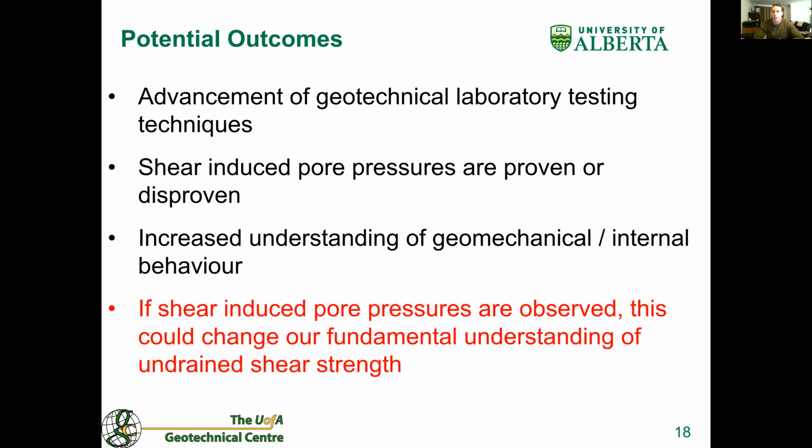This information can then be further applied to understanding the stress-strain behavior of this material, or things like damage initiation or crack propagation within deposits, for example. Finally, if shear-induced pore pressures are shown to exist, this would change how geotechnical engineers assess undrained shear strength in this class of material, specifically when strain-controlled boundary conditions exist. So we'd be changing the fundamental model for this type of material.